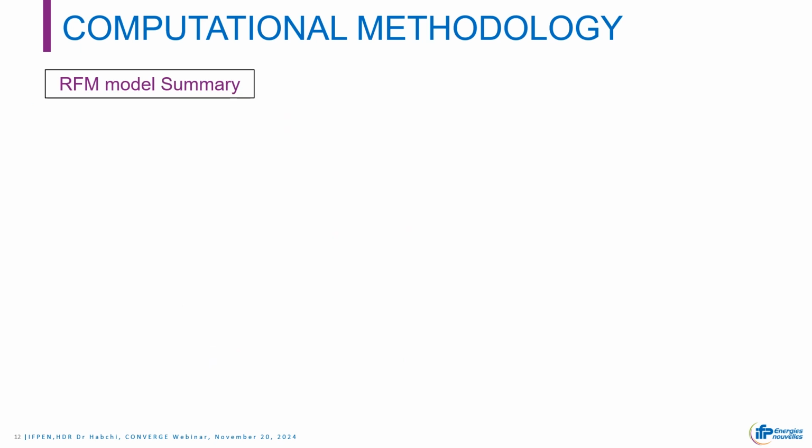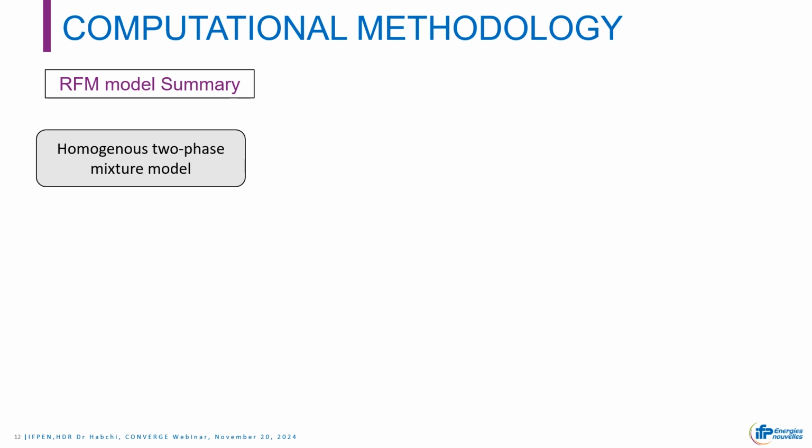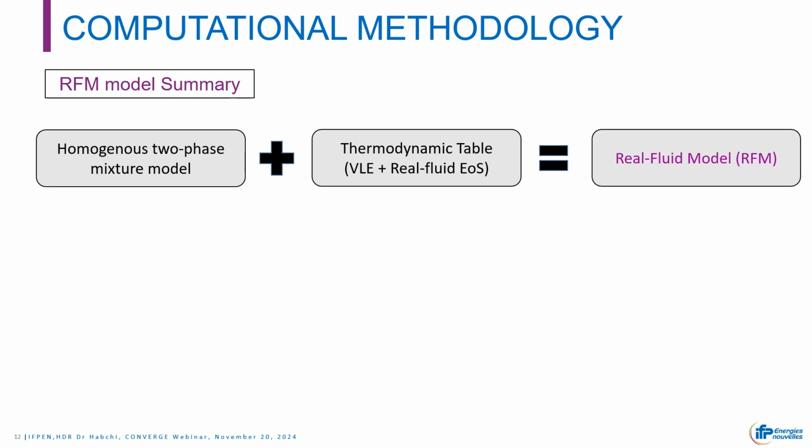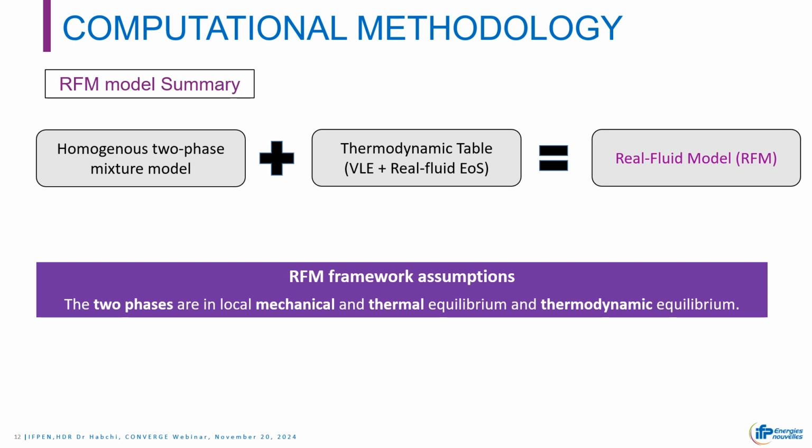So in summary, the RFM model is a homogeneous two-phase mixture model plus a thermodynamic table generated by a VLE solver using a real fluid equation of state, and all this gives the real fluid model, with the assumptions that the two phases are in local mechanical and thermal equilibrium and thermodynamic equilibrium.